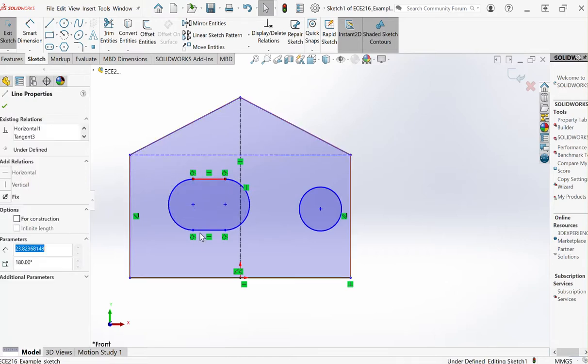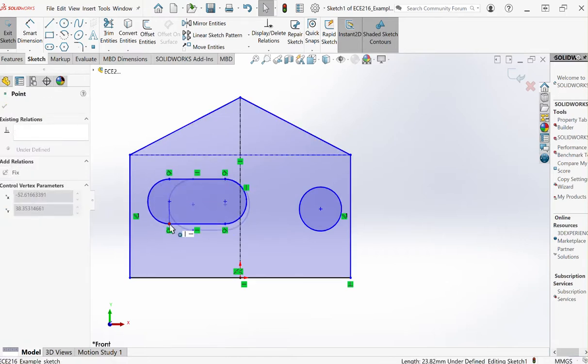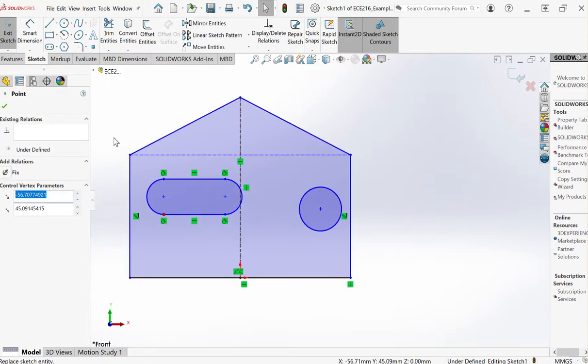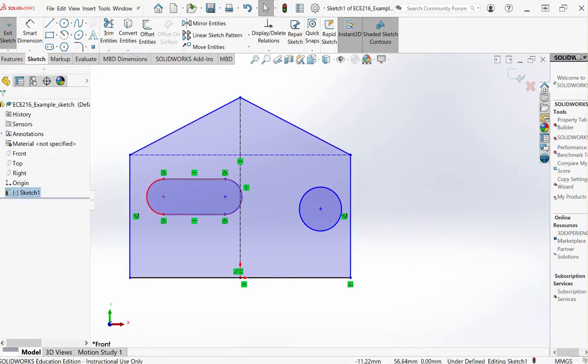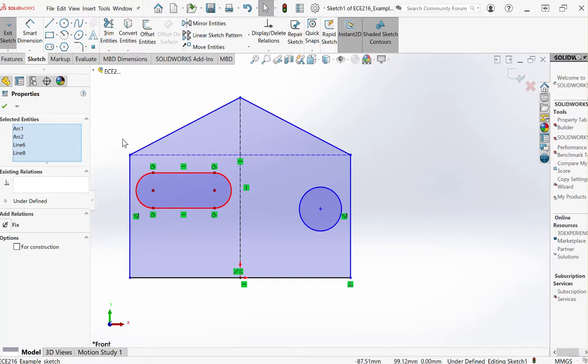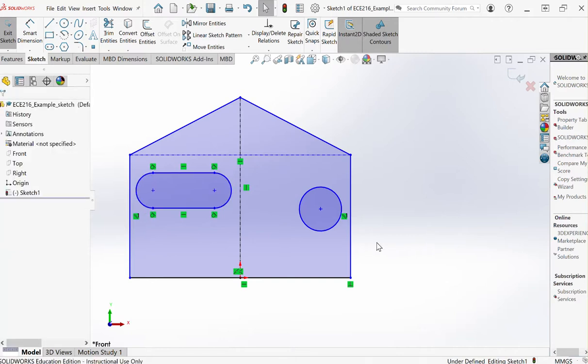They can move like this. Yeah, this stays slot, so that's correct. I think it would just miss the dimension, so we will put the dimension after. Here we go. It's still blue because we are missing dimensions. But I think we put all what I call constraints, so meaning symmetry, using axes, vertical line, horizontal line, those kind of things. Tangent between arc of circles and line, etc. Now we can begin to put the dimension.